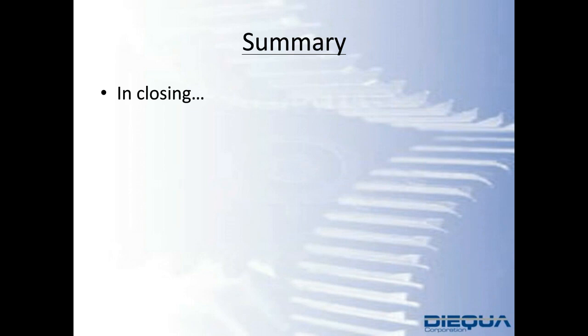Better maintenance, so reduced downtime, better cost of operating the machine, and also because you're eliminating couplings, you're eliminating high precision tolerancing on insert shafts, you're also reducing the cost of the design of the construction, right? So this is also better for purchasing, less components to document, and the list goes on as to the various benefits of the robot flanges in these gear reducers for the linear industry.